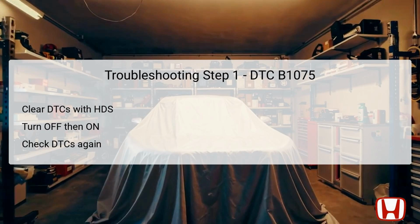The first step in troubleshooting DTC B1075 involves clearing existing Diagnostic Trouble Codes, DTCs, using the Honda Diagnostic System, HDS. By initiating this step, you reset the system's memory and can determine if the issue is persistent or an intermittent failure. After clearing the codes, the vehicle should be turned from the off lock mode to the on mode to begin fresh diagnostics. Following this, the combination light switch must be turned to the on position and waited for 6 seconds to allow the system to recalibrate.